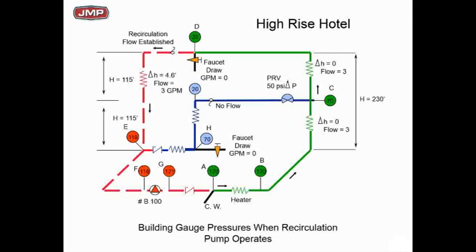We got one water heater. The pressure coming in from the pressure boost is 120 pounds. That's the green. Goes through this water heater, heats the water up for the whole building, rises up to about the 10th floor, which is about 100 feet up, and we're at 70 pounds now, and we go through a pressure reducing valve. We drop from 70 pounds down to 50, and then the hot water is fed down from that 10th floor, starting at 20 back down to the bottom at 70 pounds to all the rooms to keep the pressure below 80.